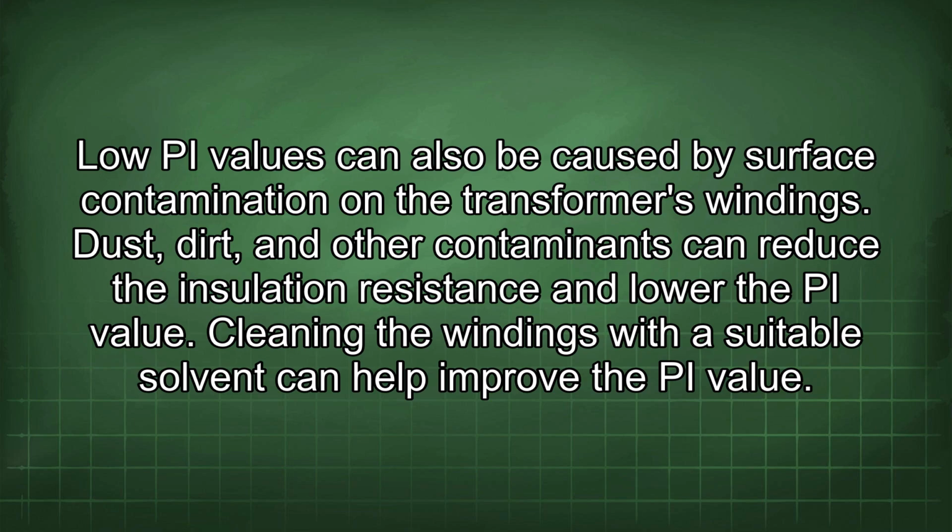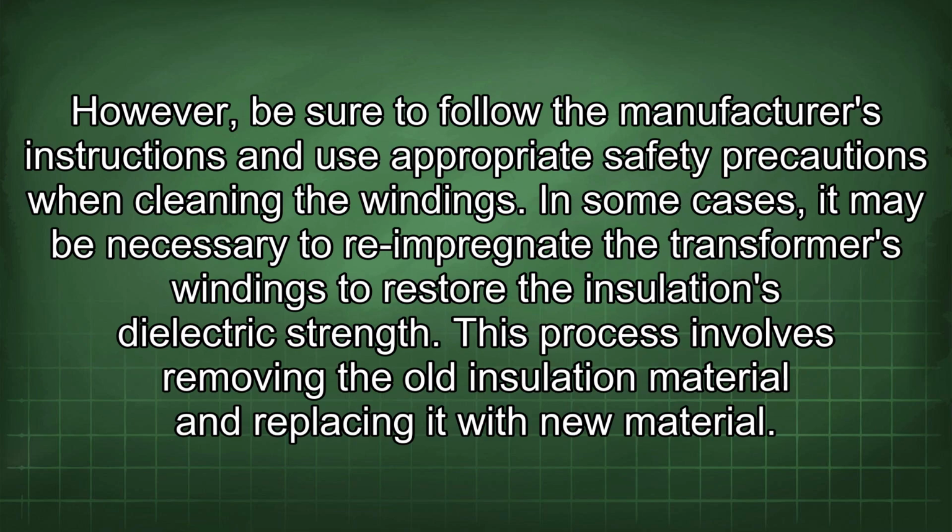Low PI values can also be caused by surface contamination on the transformer's windings. Dust, dirt, and other contaminants can reduce the insulation resistance and lower the PI value. Cleaning the windings with a suitable solvent can help improve the PI value. However, be sure to follow the manufacturer's instructions and use appropriate safety precautions when cleaning the windings.